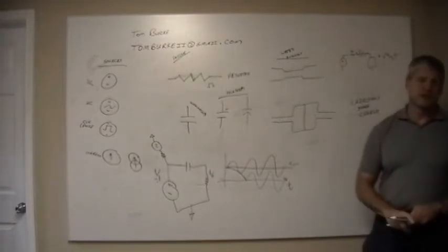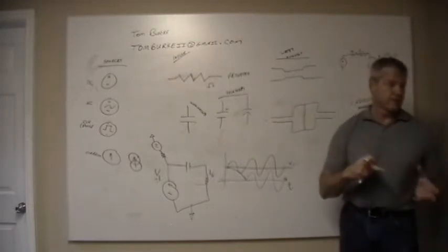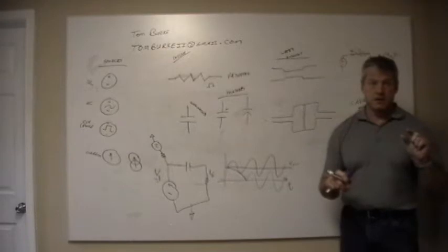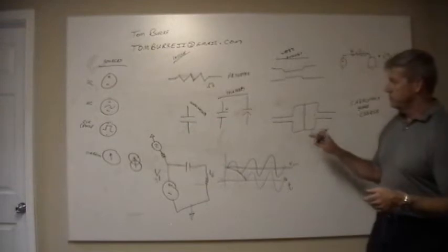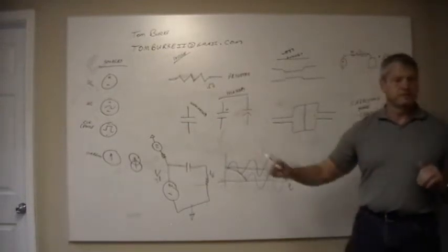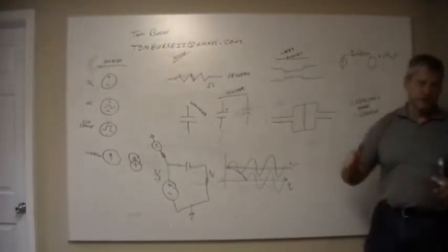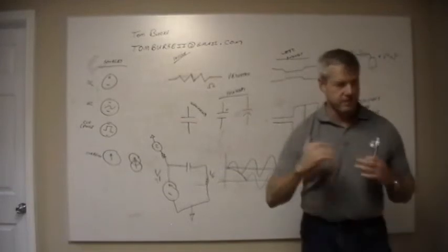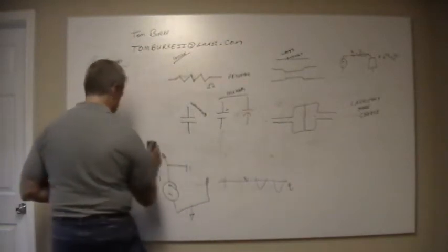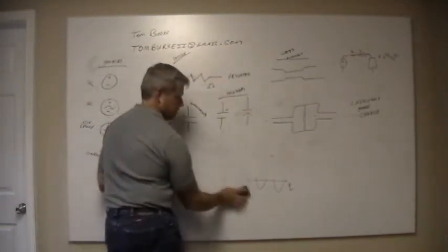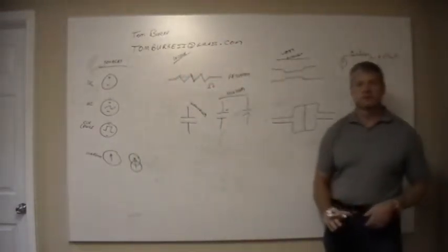Because most of the time that we use this, this is getting ahead, but in your maker projects, the electret, you usually use an electret microphone is what it's called. The microphone gives you your audio signal riding on a DC. And you've got to get that DC out of there, depending on what you're doing with it, to process your signal. And I guess a capacitor is also used for things like flashes where you store a charge and then discharge it very quickly.